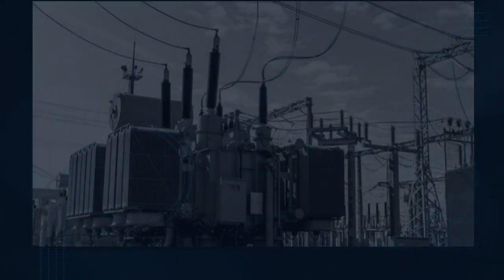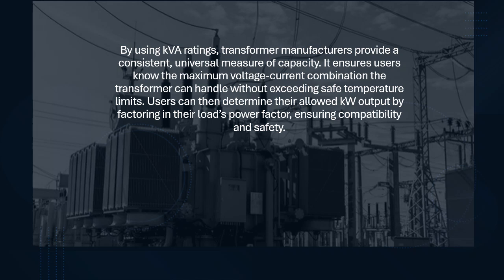By using kVA ratings, transformer manufacturers provide a consistent, universal measure of capacity. It ensures users know the maximum voltage-current combination the transformer can handle without exceeding safe temperature limits. Users can then determine their allowed kW output by factoring in their load's power factor, ensuring compatibility and safety.